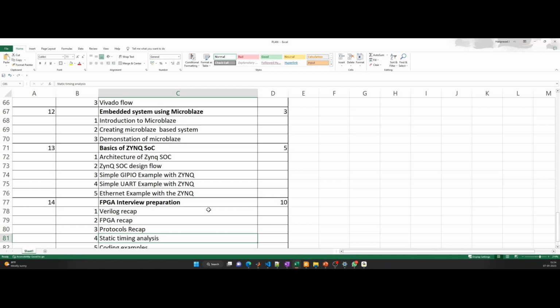You can slightly change the chip size itself, right? You can request that these gates are not fitting, so you can change the chip size. That flexibility I do not have. So when I don't have that flexibility, the logic cells can be placed anywhere for a given circuit. When we have more paths, the critical path will be longer, so more timing violations. So here timing closure is a big challenge, right? That's why we'll emphasize timing closure here and there whenever we discuss, because in the industry also you will face this issue.